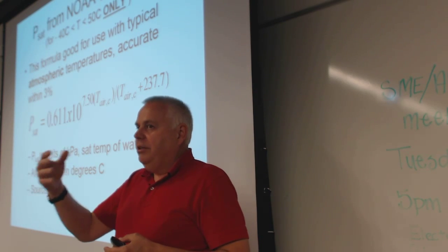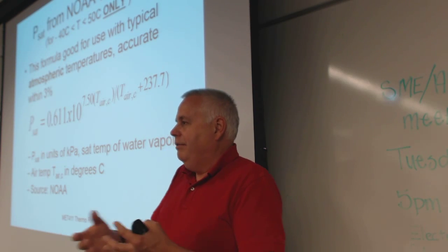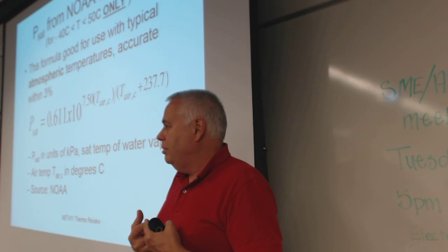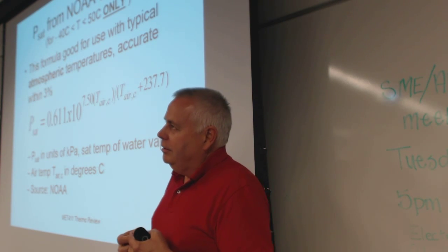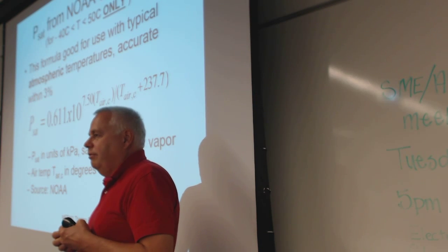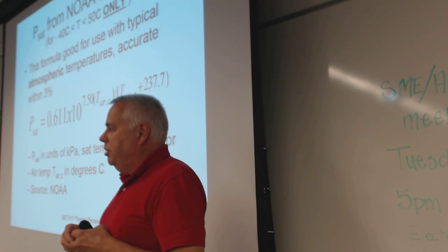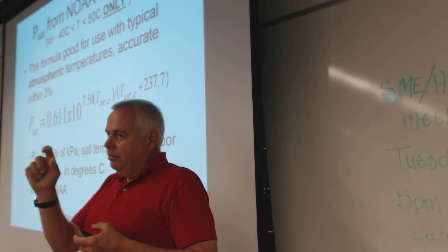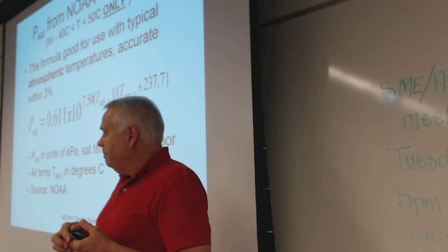Higher, and especially in summer, at higher temperatures, you get more moisture in the air. You can have a lot less dense air due to atmospheric moisture. It's not a lot. It was somewhere from 0.5% to 2% difference in the density, which if you're looking at a wind turbine and you're looking for fractions of a percent of wind turbine efficiencies, then it starts to become an issue.